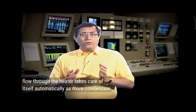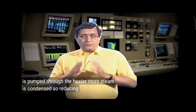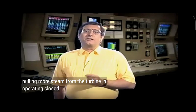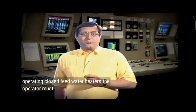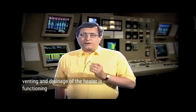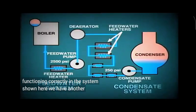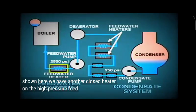As more condensate is pumped through the heater, more steam is condensed, so reducing pressure and pulling more steam from the turbine. In operating closed feedwater heaters, the operator must be sure to check that venting and drainage of the heater is functioning correctly.